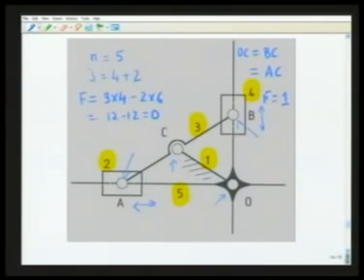In fact, as we will see, the angular velocity of link number 3 to that of link number 5, which are both rotating with respect to fixed link 1, will be exactly half for these special dimensions. This is known as cross-slider trammel, and I would like to encourage the students to show why it moves by starting from the elliptic trammel that we have discussed in an earlier lecture.